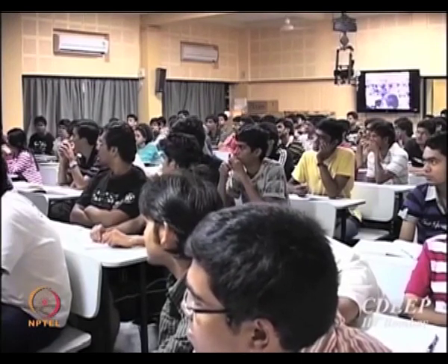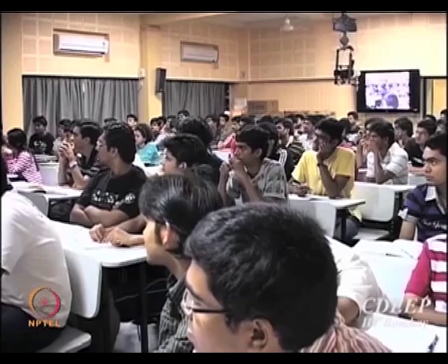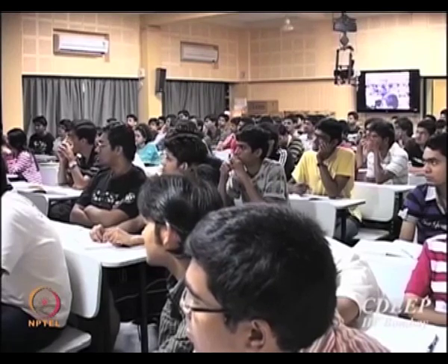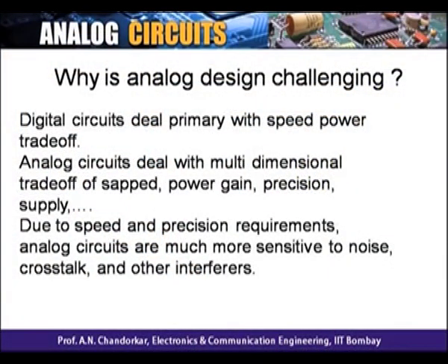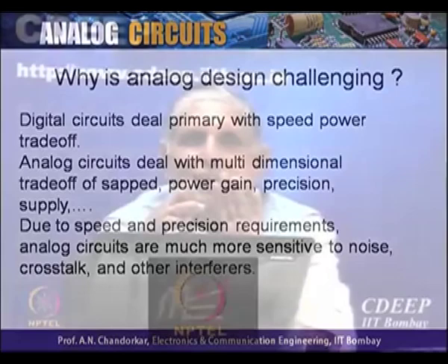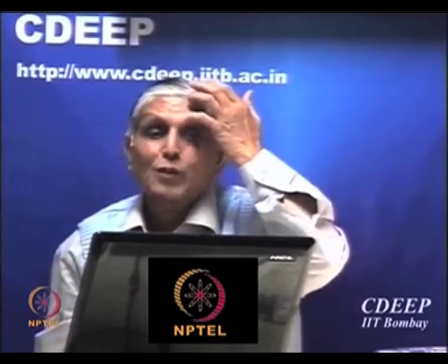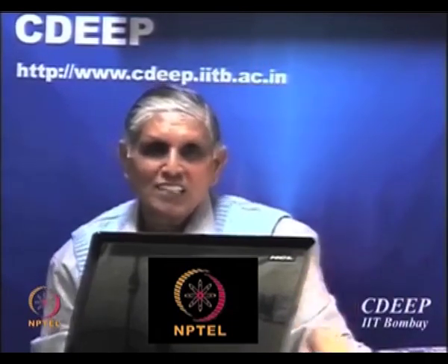The word in maths: y is equal to mx is a linear system. If I change x to 2x, y will also get doubled if m remains constant. Okay, linear systems. Is that clear? Why, therefore, were analog circuits earlier called linear circuits? Because output voltage was proportional to input voltage, gain remaining constant. Vo by Vin is constant, a straight line. Okay. So it's called a linear system.